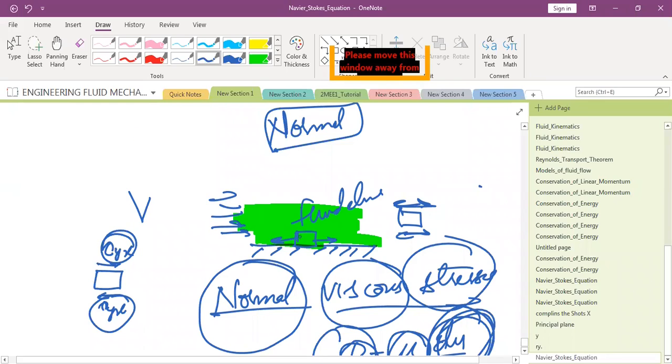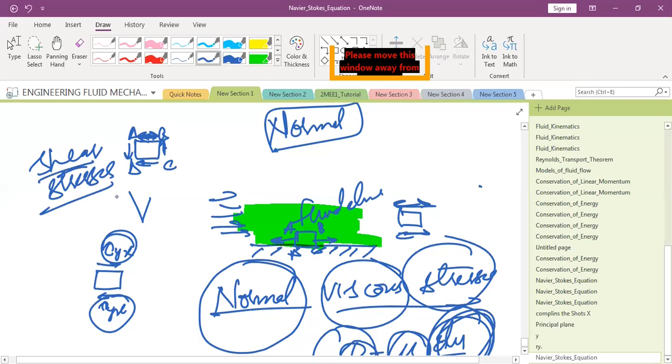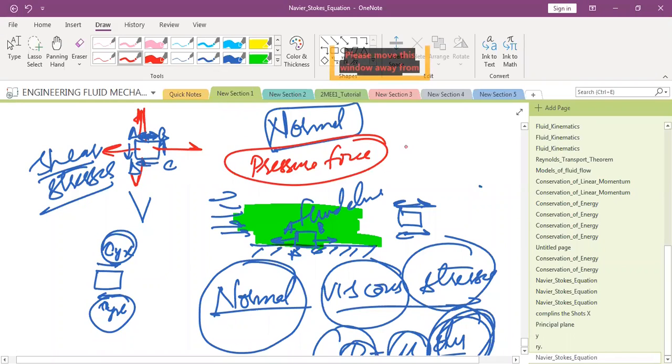Say I choose this fluid element here. Say this is A, B, C, D. So what do you know from your knowledge till date? Which faces will have shear stresses? AB and DC. You will study in solid structures also that there cannot be a single pair. There will always be two pairs. So all the faces will have shear stresses. That is one thing. Did you consider any kind of normal stresses on these? No, sir. You only considered normal stresses due to pressure force. But you never considered normal forces due to viscous forces.